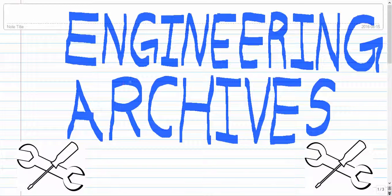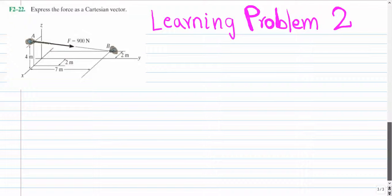Let us look at learning problem number 2 for this chapter, force vectors. So this question says, express the force as a Cartesian vector. In order to express this force as a Cartesian vector, we will have to go through the regular process that we discussed in the previous question. And that process is to first find the length vector r, then use that to find the unit vector, and then use that to find the force vector F.